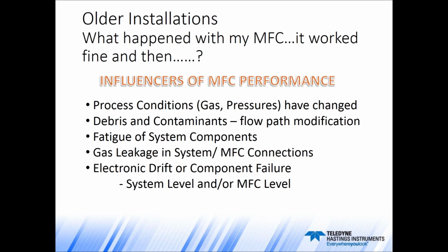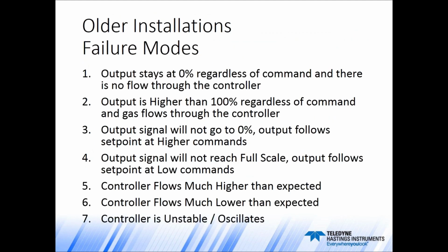Fatigue of system components, it's something that will affect the performance of the flow controllers in any gas line. Gas leakage in system or in MFC connections. And finally, electronic drift or component failure at both system level and MFC level will influence the behavior of the flow controller.